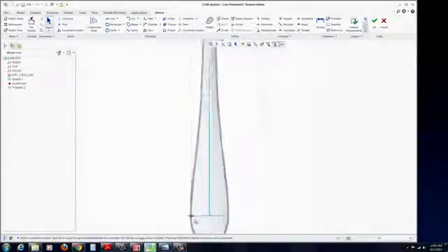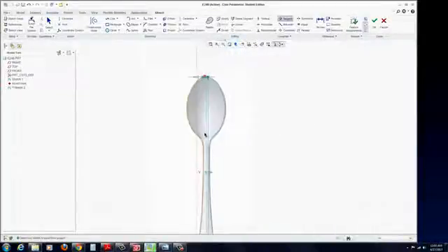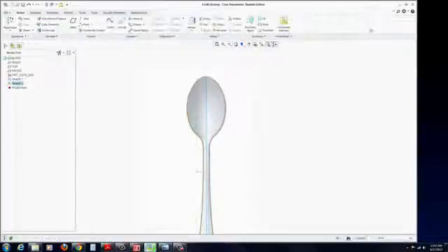Just make sure you didn't jazz anything up too much here. Okay, let's move it over. And finally, go to tangent under constraint and add a tangent constraint between your spline and the vertical center line. And that's it. Hit the green check mark. So now we have our outer edge.